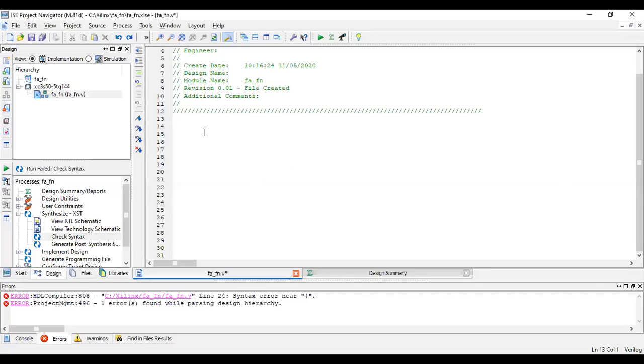You're going to see a ripple carry adder. Let me take a 4-bit ripple carry adder where the full adder is defined as a function, and in turn the full adder is calling the half adder as a function. Now for a ripple carry adder, what do we have? We again will be having the inputs A, B, C in. C in I will take, and I'll have the outputs sum and C out.